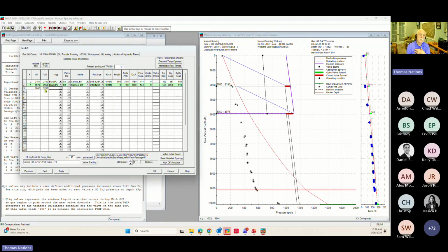Push the enter key. It knows to update that because of the wellbore description and the deviation survey. I'm going to choose a bellows valve. I'm going to choose a 1-inch valve. I'm going to choose this is the list of valves that we have in our drop-down, in our catalog. And these are valves that have been flow tested by the Valve Performance Clearinghouse.